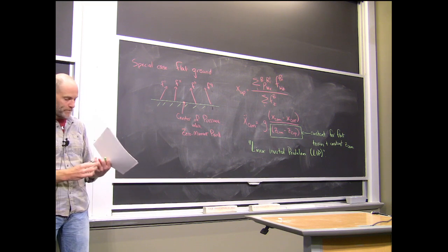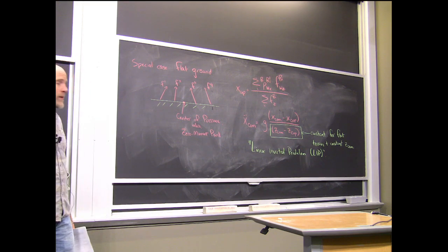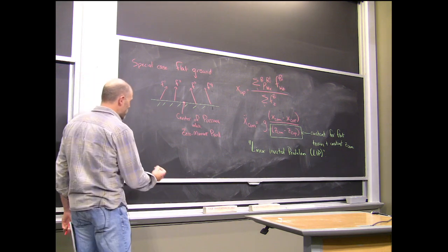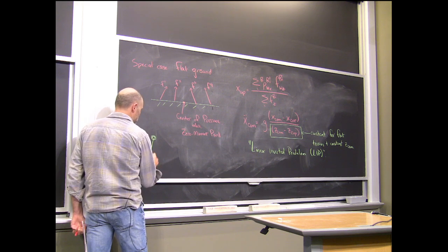Just to tie the pendulum part together, you basically have a triangle where the vertical component is equal and opposite to the weight, right? And then the hypotenuse is the total force, and the horizontal component is what accelerates you. Let me say it back to you. The normal inverted pendulum looks like this with an angle.